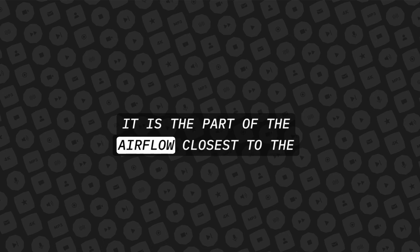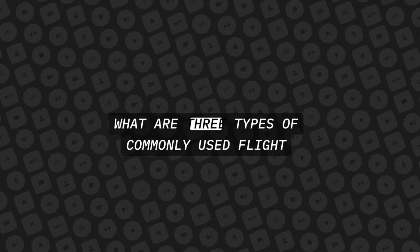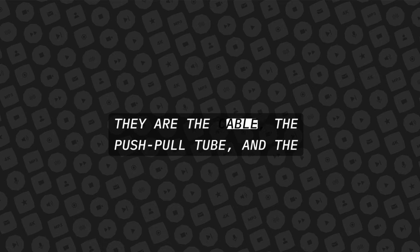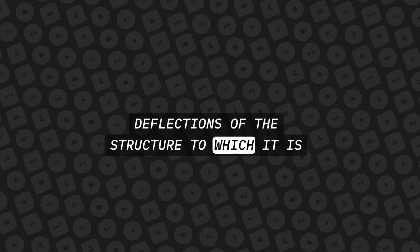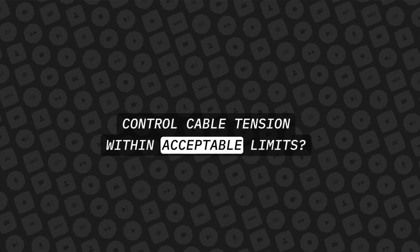In relation to an aircraft, what is the boundary layer? It is the part of the airflow closest to the surface of the aircraft. What are three types of commonly used flight control systems? They are the cable, the push-pull tube, and the torque tube systems. The cable system is the most widely used because deflections of the structure to which it is attached do not affect its operation.